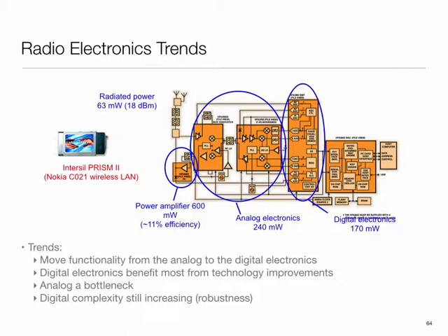And there are a couple of things. Firstly, unless I have a very directed antenna, a lot of energy is going in directions in space where no one is listening. So that's one issue. The other is that amplifiers can be very, very inefficient. The reason they can be very inefficient is that the way we send the signal sometimes requires that the amplifier be linear.